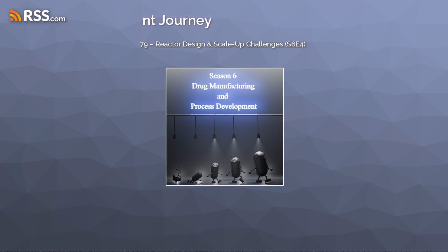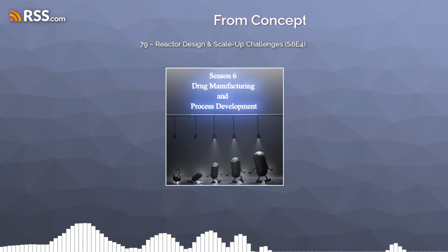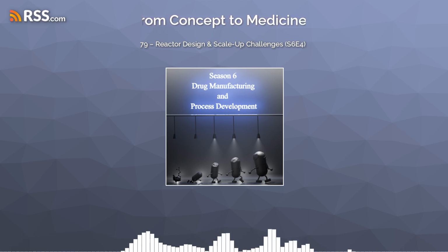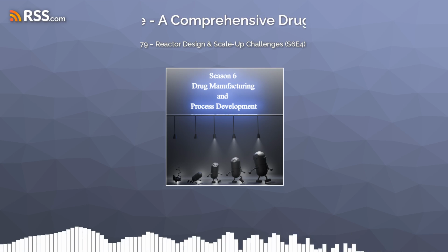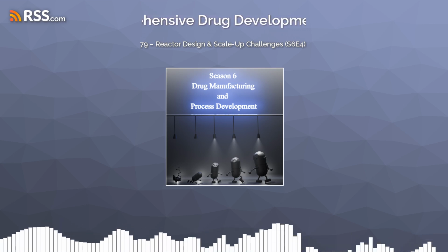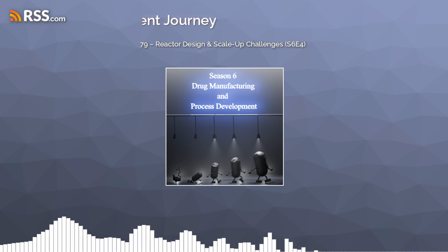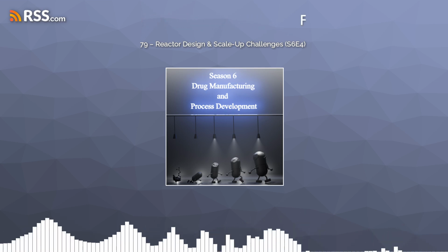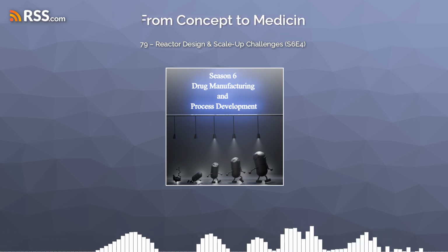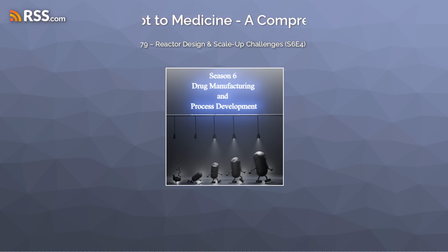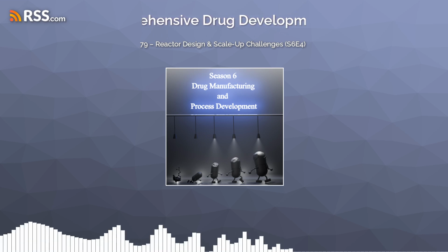Yeah, that's really cool. All right, so we've covered a lot of ground today. Let's take a moment to just summarize the key takeaways here. Okay. So we've seen that scaling up a chemical reaction is a lot more complicated than just multiplying everything by a factor of 10 or 100. Right. There are all these new challenges that you have to deal with. Yeah, absolutely. And one of the biggest ones is heat transfer. Right. As a reactor gets bigger, it gets harder and harder to get the heat in or out. Yeah, and that can lead to all sorts of problems like temperature gradients and runaway reactions.